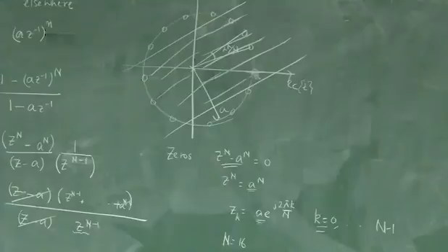Okay? So another point I just want to reiterate is that whenever you specify the Z transform, not only should you specify this equation here, but you also must specify the region of convergence, right? Because without that, this becomes meaningless. We already showed that with the example of the right-sided sequence and left-sided sequence having the same Z transform and the same set of zeros and poles. But if we didn't specify the ROC clearly, then you could end up with the wrong inverse Z transform, right? Okay? Any questions?